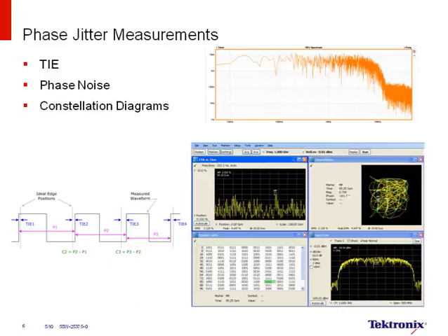All the other points at 1 hertz, 10 hertz, 20, 25, all are different jitter frequencies, if you will. So the way you want to correlate from the phase noise measurement to jitter is to think of phase noise at multiple offsets. And all those other multiple offsets are also jitter components.